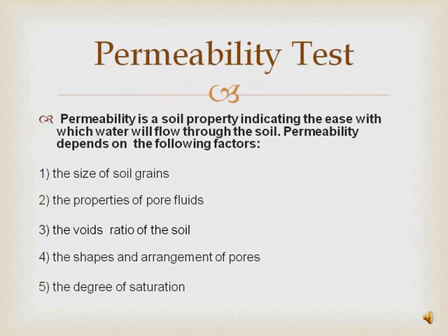Permeability is a soil property indicating the ease with which water will flow through soil. Permeability depends on the following factors: the size of soil grains, the properties of pore fluids, the void ratio of the soil, the shape and arrangement of pores, and the degree of saturation.